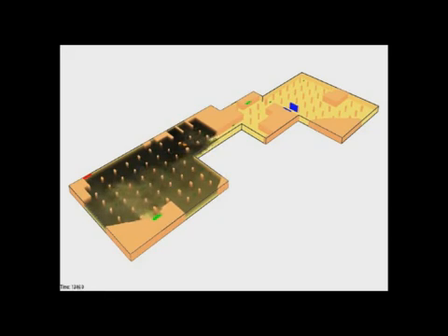There is this car here, and these jet fans, which are an alternative to duct ventilation, are installed here. The thing about car parking is, for duct ventilation you don't need CFD that much, because the duct will guide the smoke the way it should go. But if you have to use a jet fan, then to ensure that the jet fan directs the smoke in the right direction, we need to do CFD analysis. Otherwise, the design might not be good.